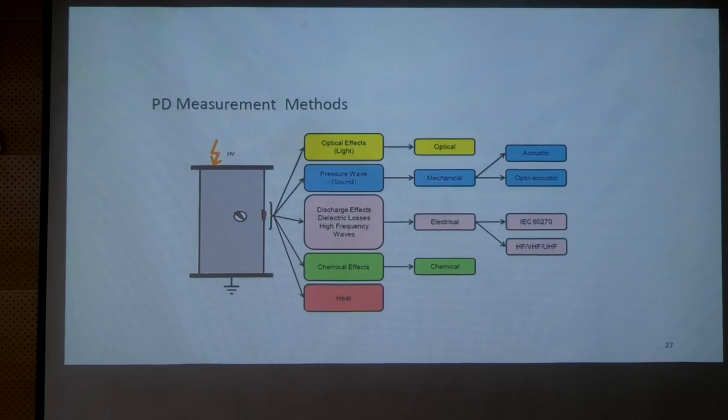These partial discharges will have different manifestations. They can emit light, so we can use optical techniques and optical sensors, which we can easily place wherever this is observable. These are all electrical discharges, occurring because the insulation cannot withstand the electrical stress and so it discharges.